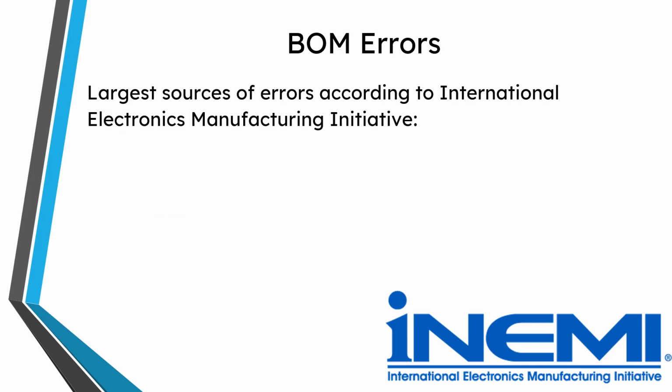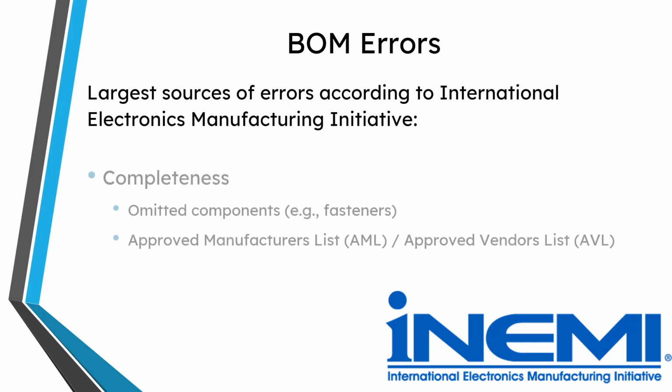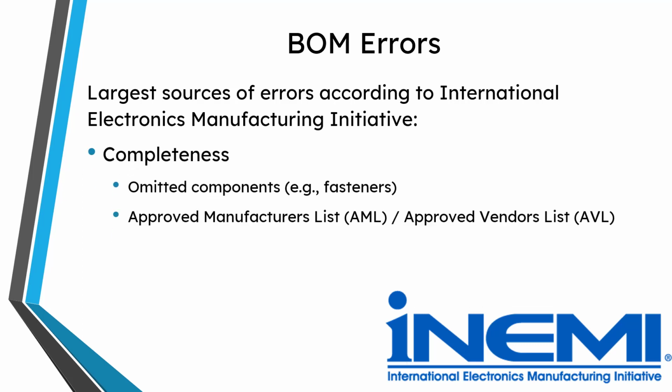According to a group called INEMI, there are three main sources for errors in your bill of materials. First, there's completeness. Oftentimes when people are putting together your engineering bill of materials, they might forget to include certain components. Maybe they might forget some fasteners. Maybe they might forget some helical inserts. Also, people might not have their approved manufacturing list, the AML, or the approved vendor list completed.